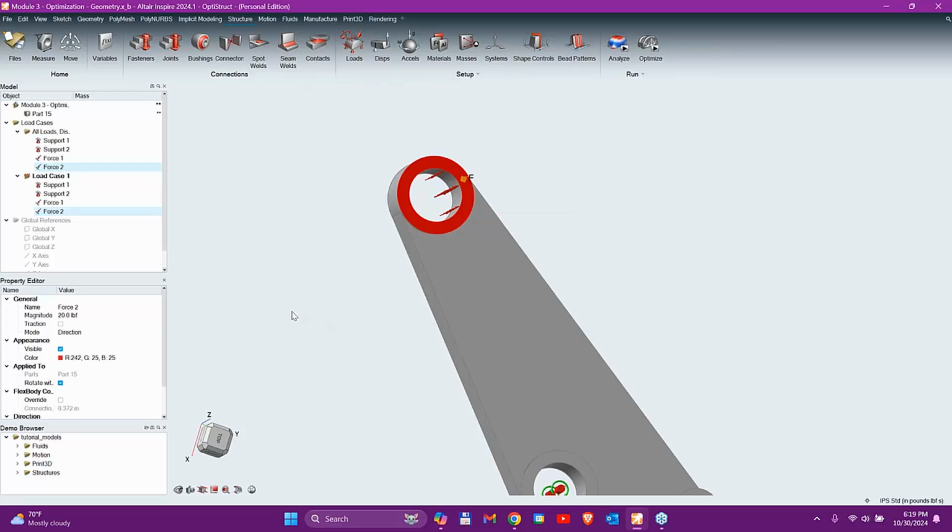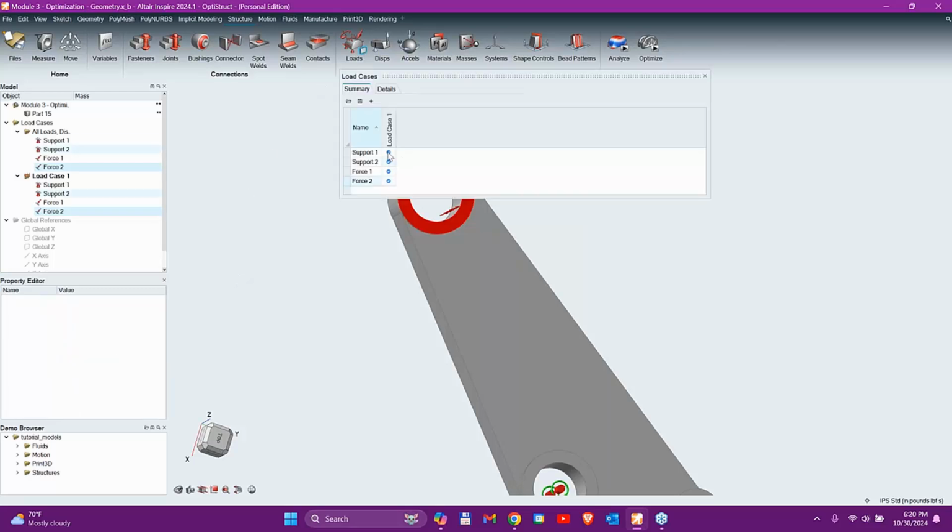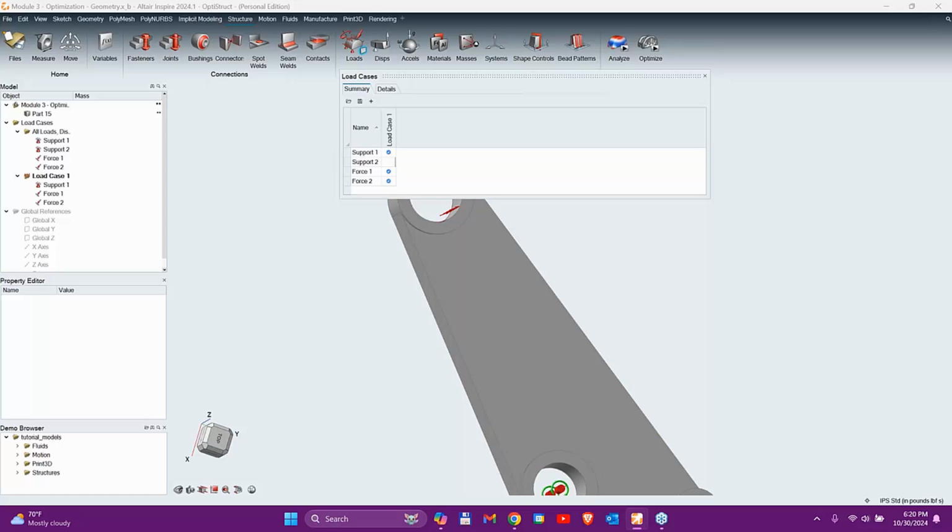And then I can even define multiple simulations. So I can say, okay, this load case is going to have my bearing load in it, but not the side force. And I can create a secondary one where I use my two supports and I just analyze the side force. And I can create a third one where I utilize my two supports and maybe both forces are occurring at it.